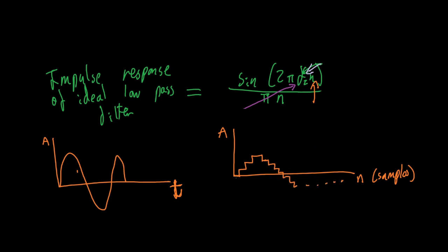Etc. You see, it sort of makes a sine wave look, but it's more of a staircase, isn't it? But that is how a computer would see it. And each of these would be samples. So that'd be n equals 0, sample 1, sample 2, sample 3, sample 4, sample 5, etc. It doesn't look at it as in t equals 0 to t equals infinity.